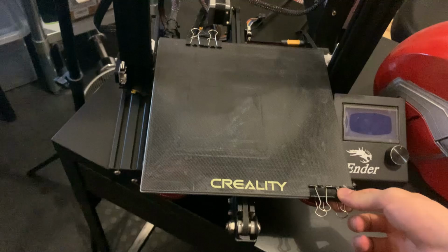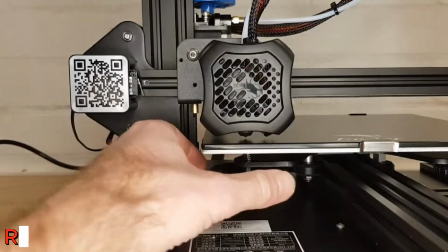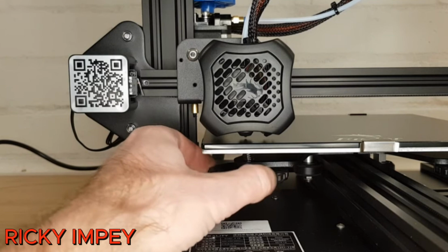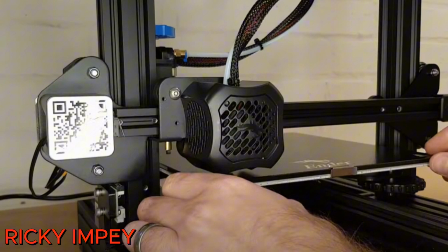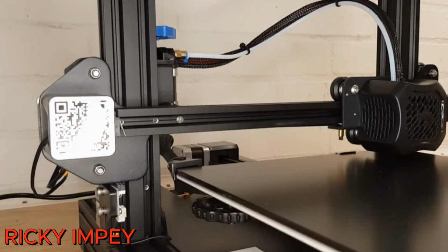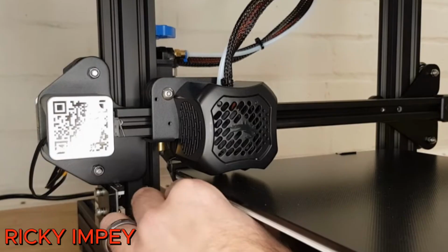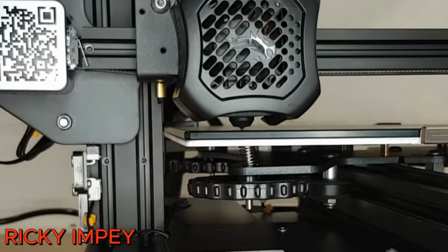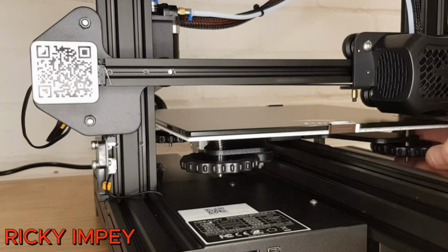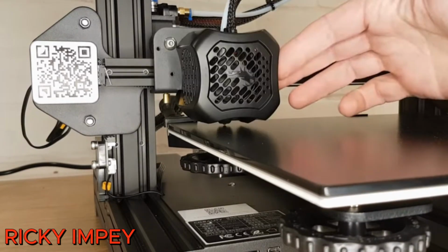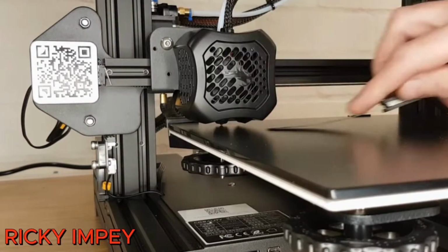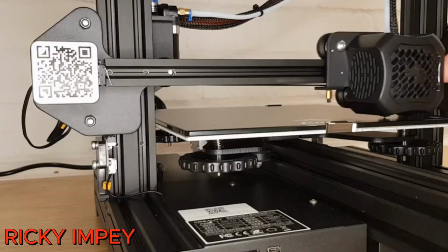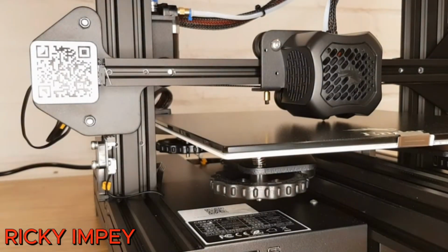So another thing you guys need to keep in mind, which is really important, is the level of your bed. This is a crucial step when 3D printing. Nowadays, 3D printers already have a bed leveling system. However, some older 3D models and some newer ones that are cheaper have a manual bed leveling system. And trust me, if you have never manually leveled a bed before, you're about to feel some serious pain. But that's all right, don't worry. There are several YouTube tutorials out there that you guys can look at for how to level a bed manually. You just need to know that no matter what kind of printer you have, your bed needs to be leveled. Otherwise, this will lead to several issues that are gonna happen throughout the print.